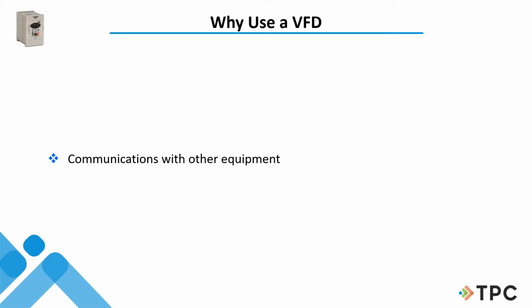This is something that is much better than across the line motor starters, is the communication. Motor starters, the old ones, we usually know when they trip out, and we know when we turn them on, and we get that information from auxiliary contacts. But with a solid state drive and VFDs, we can communicate through the PLC, RS-485 communication ports, and it is so much easier to program through that system. I don't have to go to the drive and work off a pad on the drive. I can do it right off a computer someplace.